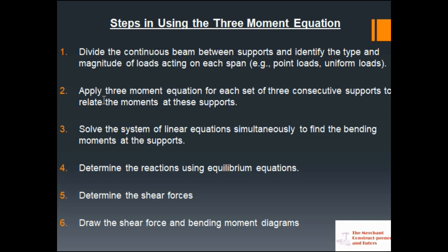Depending on the number of spans in your continuous beam, that will help you determine whether you are going to use simultaneous equations or a matrix method to solve. So solve the system of linear equations simultaneously to find the bending moments at the supports. You understand what simultaneous equations are. Now you determine the reactions using equilibrium equations. Also determine the shear force and the maximum bending moments.